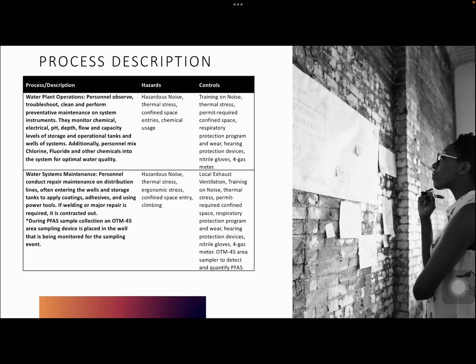Additionally, they can add fluoride for dental purposes in children and older and young adults for optimal water quality. Some hazards with this process are noise, thermal stress, confined space entries, and chemical usage, and here are some controls that I had for this scenario: noise training, thermal stress controls, permit-required confined space, respiratory protection, PPE, ear protection devices, and a four-gas meter.